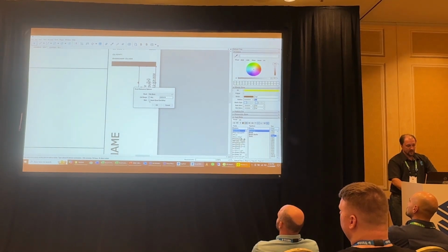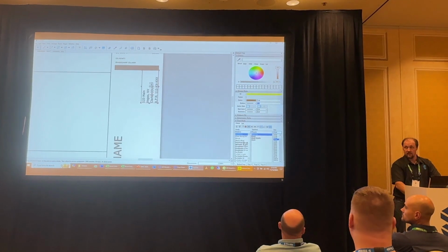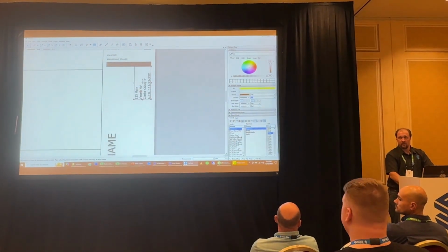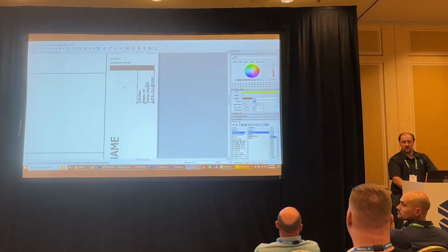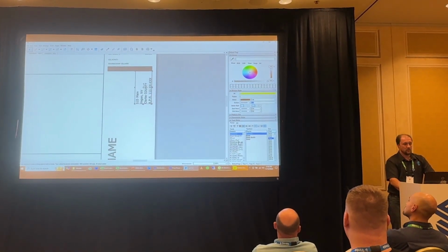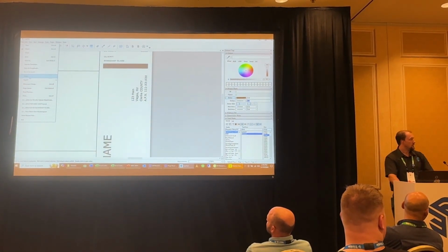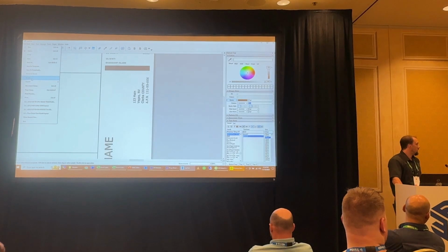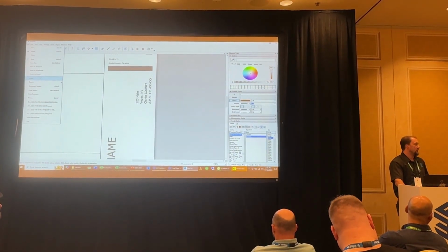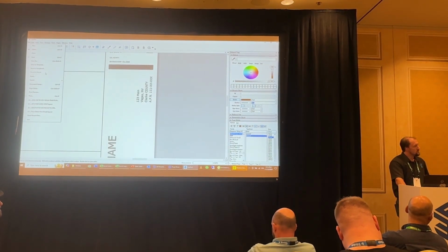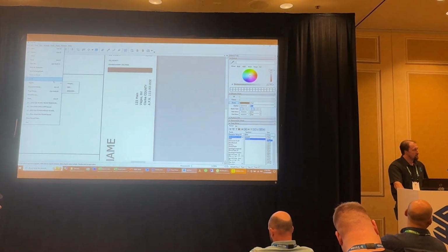This import Excel formatting, just turn it off. Yeah, I haven't seen that before. That's when you reference it. Are you referencing or are you inserting? I was just copy pasting. Oh, okay. Do it as an insert. Insert the file, up here. One of the other options that I did was I created a template in SketchUp for the formatting of the schedule I want, and then I overlay it with the Excel one so I can white out lines or shades in between.